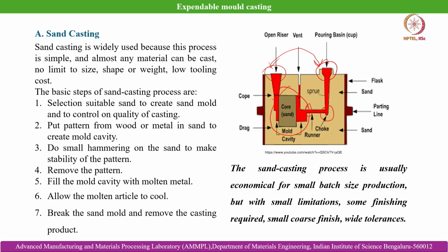Please recall that I told earlier that core sand is of slightly improved quality than the sand utilized for the sand mold making, and we also use specific types of binders to bind the core sand, so that we can get the desired core geometry, and accordingly the corresponding hollow shapes can be made within the cast parts after solidification.